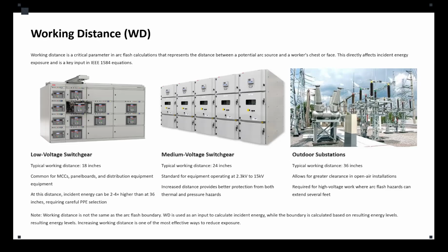Typical working distance is 18 inches, which is about 455 millimeters. The common equipment are MCCs, the motor control centers, panel boards or switchboards.